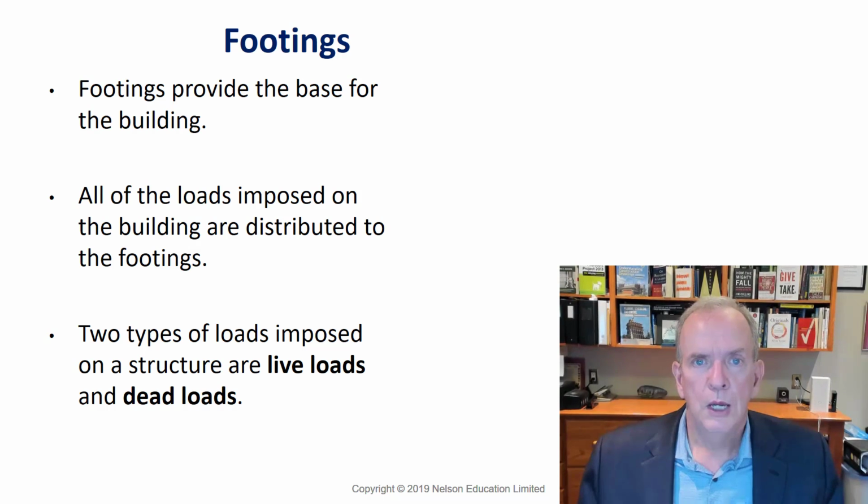We have to think about things such as the snow loads and how it varies from community to community, town to town. So Thunder Bay would be different than Toronto. Collingwood would be different than Toronto. Government has tracked historically the amount of snow that falls in particular areas, and they designed the snow loads around 100-year worst storm cases.